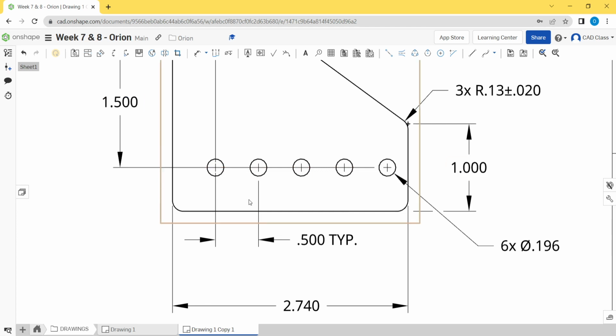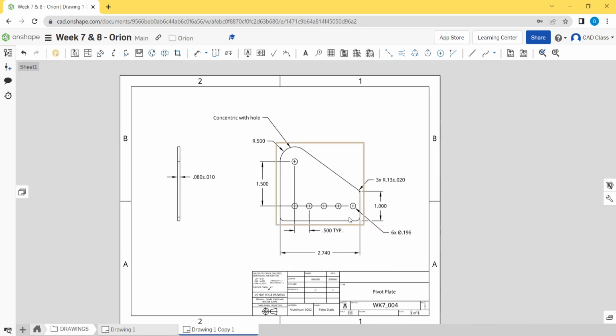Basically, if all of the tolerances end up towards the high side where they're a little bit oversized, or if they all end up on the low side, I can have these big swings in dimension at the end. And that's a really big problem. A very big part of engineering is managing that tolerance stack up.